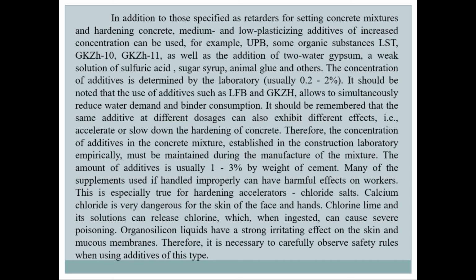Chlorine lime and its solution can release chlorine, which, when inhaled, can cause severe poisoning. Organosilicon liquids have a strong irritating effect on the skin and mucous membranes. Therefore, it is necessary to carefully observe safety rules when using additives of this type.